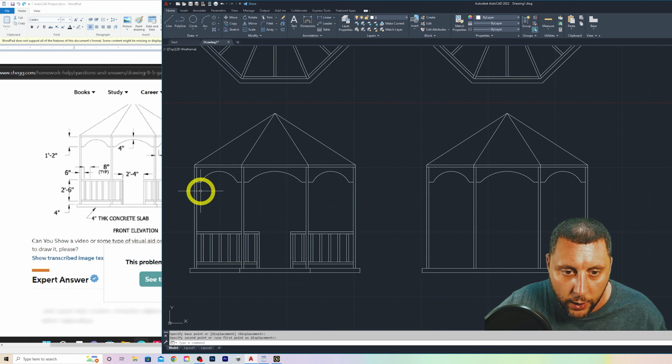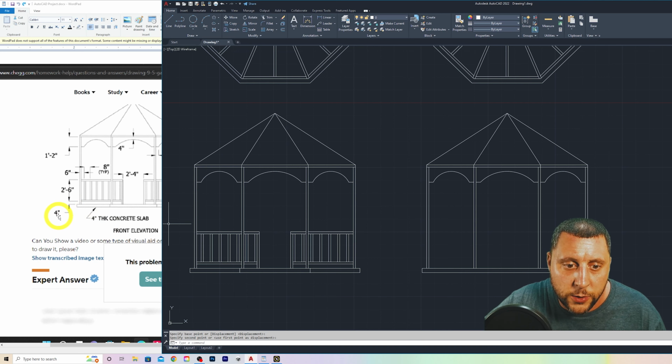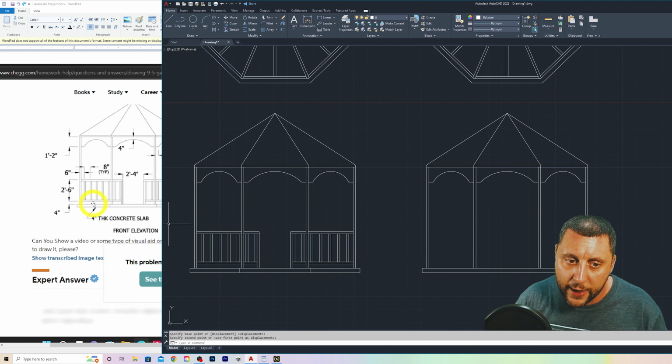So that part's done. Railing, here we go. Standard railing height of 2 feet 10, which is 34 inches. 34, 36 is actually usually standard for the stuff that we do, but very close. So I added that because I got a 2'6" here and I've got a 4-inch here. So this 4 inches is saying that the spacing under the railing is 4 inches, and that's standard because it can't be any bigger than that. Because they don't want like a small child falling through there, okay?